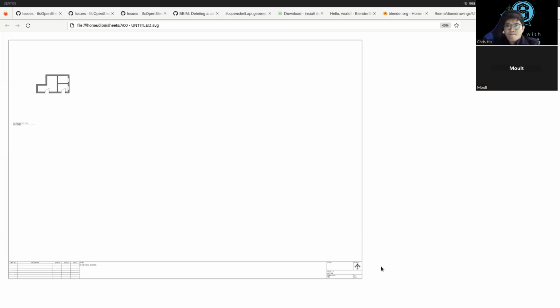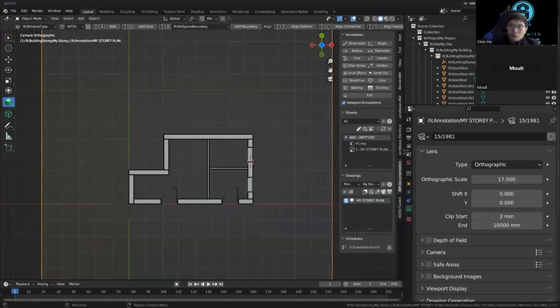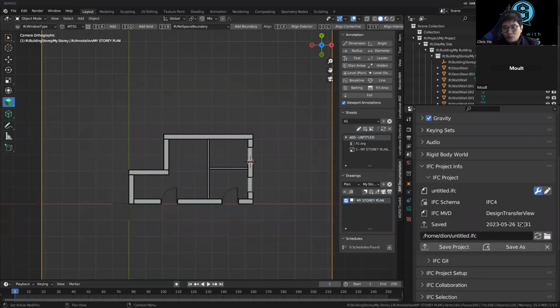Absolutely. I think many people have only ever used IFC in a very superficial sense, almost like the vendors keep on describing it like a PDF, which is extremely incorrect. As you can see here, this is the opposite of a PDF. This is a really rich environment. And just now you saw me save the model, and there was no time at all in saving it, because I'll just save it again, right? I press it and it's done. It's instant. There's no export required. There's no translation. There's no data loss. It already is IFC. You're just marking it as a snapshot in time.